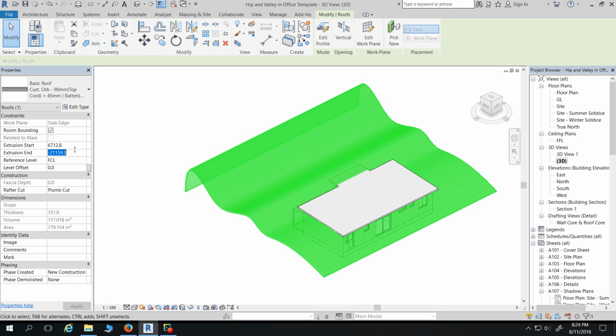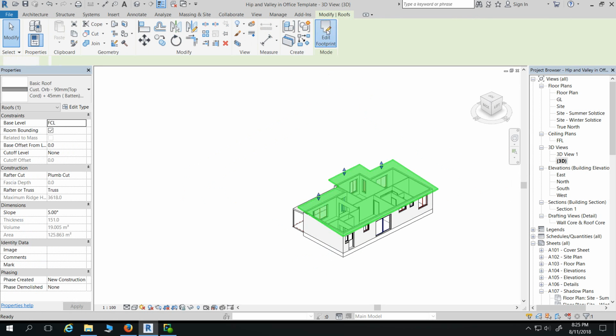Some roofs I've drawn have got 3 or 4 roofs in the one roof. What about merging a skinny roof into a hip roof, like for a lean-to or something like that? Either a lean-to or an extension, or if you're trying to have a rake ceiling in the back and you want to have a hip roof in the front, or do something else funky like that. I don't know, it'd probably be a lot of trial and error. I'd probably use the roof by footprint tool and just build 2 separate roofs together.